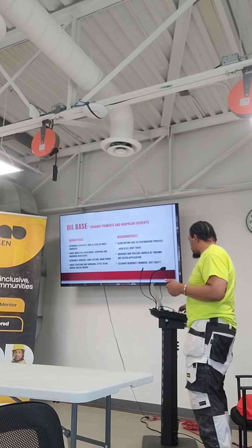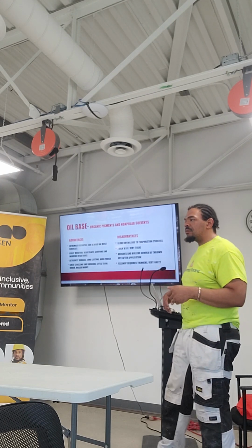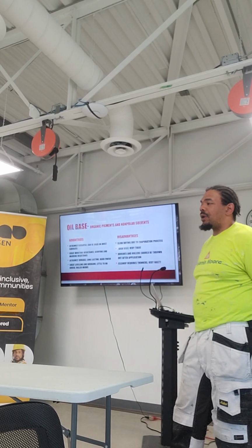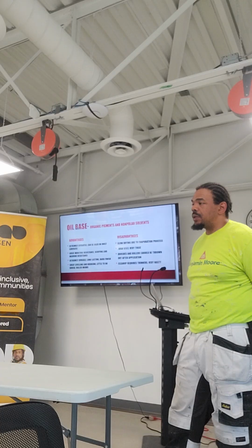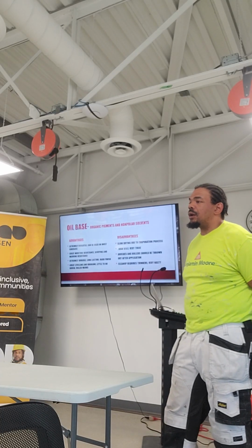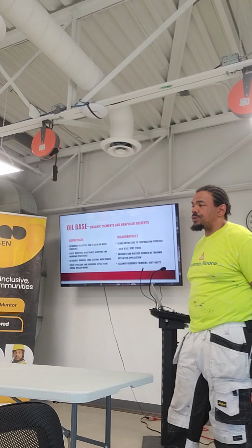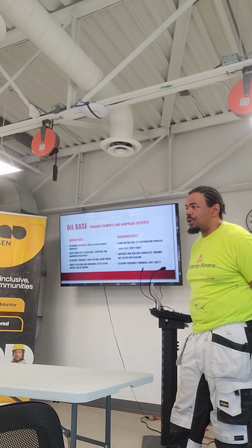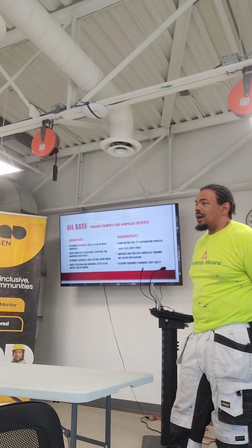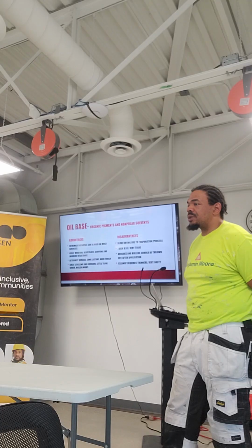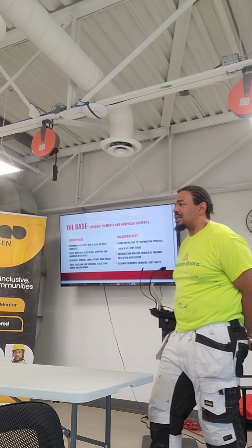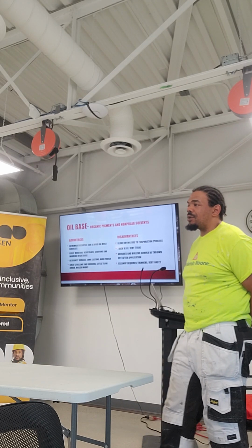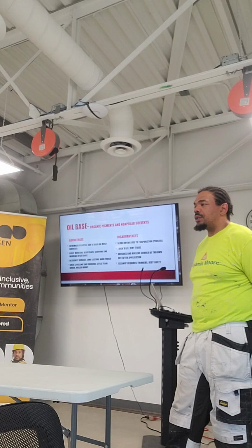So would you say to use oil paint on the outside, because you don't have to go back for a long time? I wouldn't use oil paint outside because it's organic, right? So it will form mold, and it will form mildew. Oil paint promotes mold and mildew because it's an organic compound, right? So mold and stuff is attracted to it. So unless it's on metal, something that's non-ferrous metal, that means it doesn't breathe, then you can use oil on that. But you should not use oil on concrete. You should not use oil on wood outside.